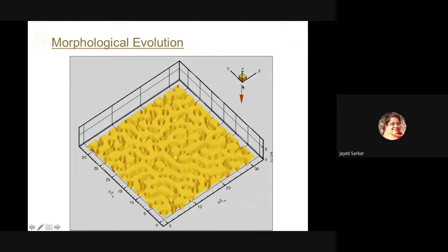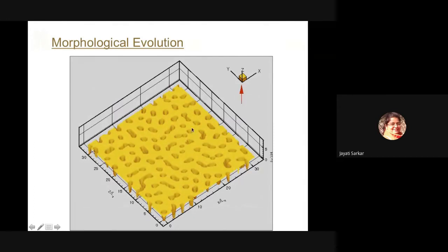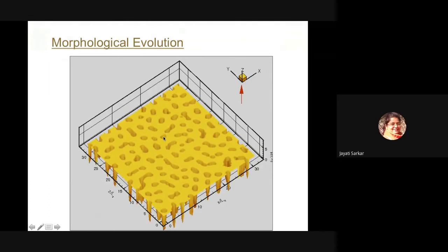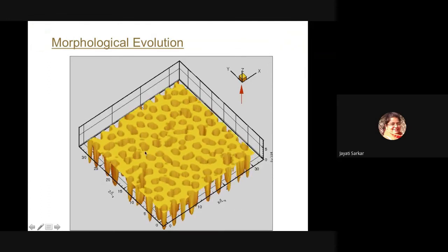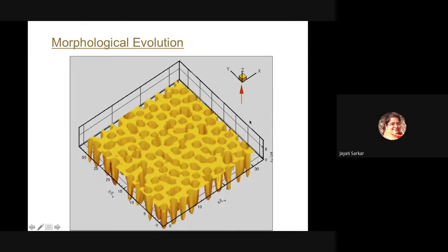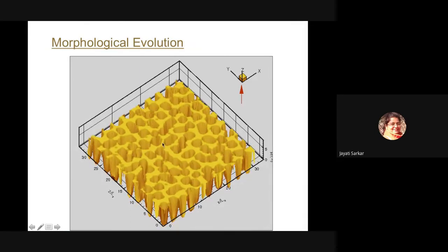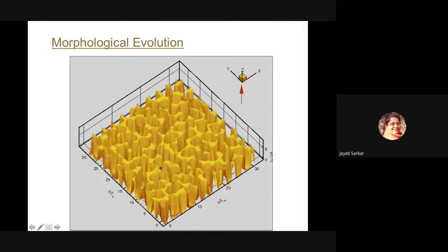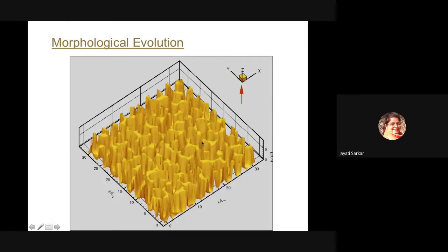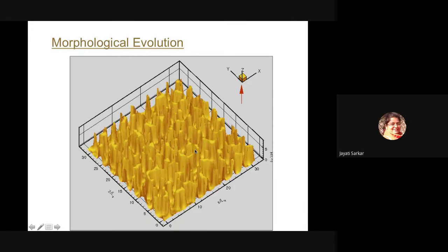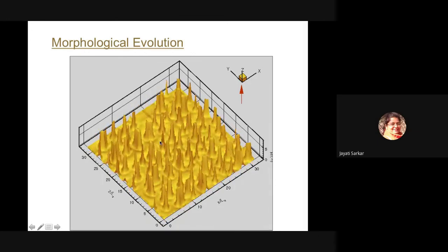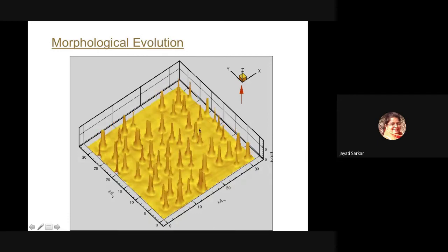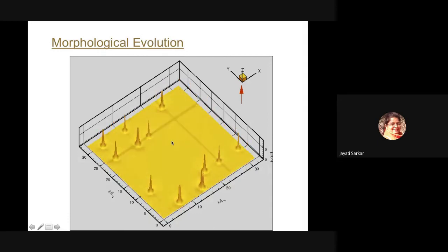So if you do the nonlinear analysis, that is what is happening here. The red arrow marks how the contactor is being pushed down. So here you can see that when we had pushed down, there was a wavelength, and these were the cavities that were forming, which forms a dispersed phase. And now you're pulling the contactor up. So this is the surface of the film that we are seeing. There's a virtual contactor on top of this that is pulling the elastic surface up, and you can see now that these cavities have all connected, and this is giving rise to a columnar-like structure, and after some time the columns snap back and give you the flat film configuration.